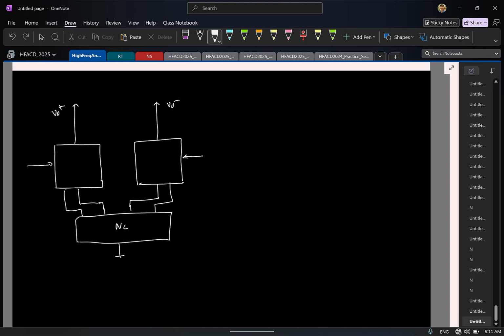So that means the input is basically shorted. And the same procedure, I will find the total noise in the output, either in the short circuit output current or in open circuit voltage. Here I look at the voltage because that's easy to see here. And then I'll divide it by the overall transfer function from input to output. So let's break it down into multiple pieces.